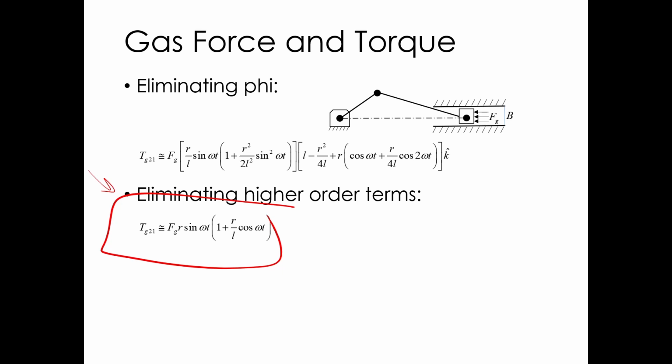It includes the effect of the connecting rod center of mass. It includes the crank center of mass location. If we could put a model for force up here in the piston, and we could calculate reaction, the shaking torque, including the force from the piston, the gas pressure too, right? And we're not losing all the stuff we lose in this assumption. So there's a limitation to all models, and at this point we're sort of pushing this one a little too